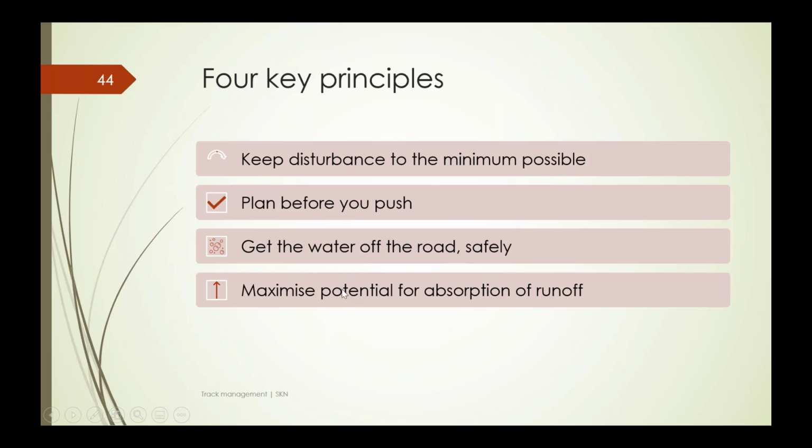And then once the water is off the road, the sediment-laden water is running out over the forest compartment, we want to maximise the potential for absorption. And so we're looking really at you to identify the sites where water will spread out rather than concentrate, and where it has the opportunity to infiltrate, and therefore to prevent that sediment getting down into the watercourses.